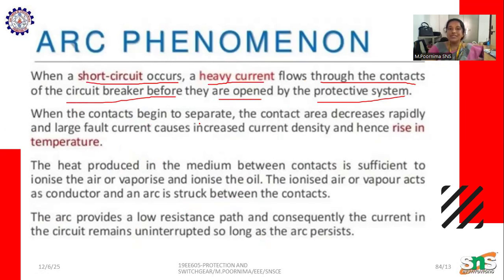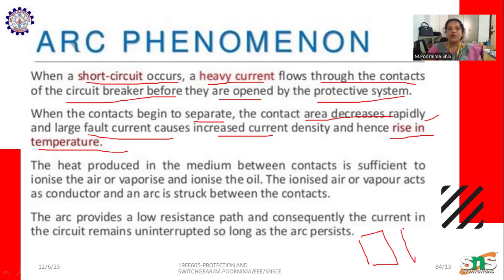When the contacts are being separated, the contact area decreases rapidly, and the large fault current causes increased current density and hence a rise in temperature. We have already discussed that the large fault current increases the current density, and automatically the temperature rises.